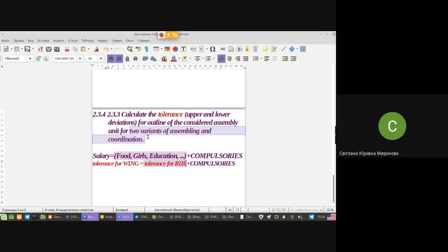Normally, you take the method by outer surface, I mean by skin, because the first part you are trying to locate is usually the cap or rim, or if it comes to a panel, the first part will be the skin. It means that you are using this technique, locating onto the outer surface of skin, even if you have no skin in your assembly unit. It's just the name of the method, no more.